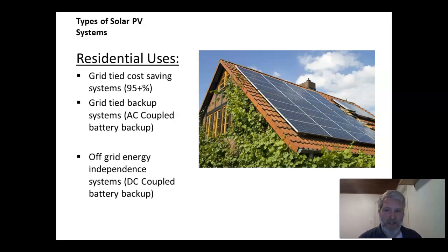We call those AC coupled systems. And then we have off-grid energy dependent, which is a DC coupled battery backup system, which is the traditional battery backup system that has your modules, a solar charge controller, batteries, inverter, and then your essential load panel.